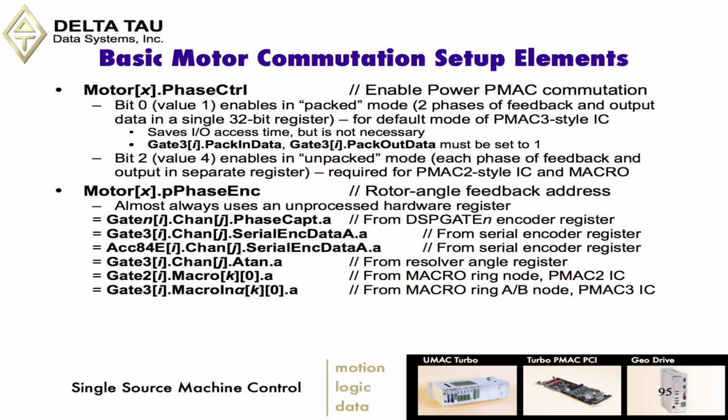So you see the display that's blinking here. I can read these values back over one of the ADC registers. Anytime the drive goes into a fault, I can read the fault values back. I can also read the status of the motor thermal elements on that drive. But if I put it into pack mode, now the ADCs are being used differently, and I no longer can access those features of the drive, even though it'll still function.